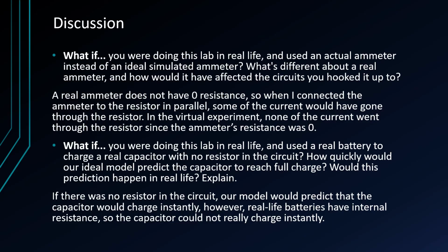What if you did this lab with a real ammeter? A real ammeter does not have zero resistance, so when I connected the ammeter to the resistor in parallel, some of the current would have gone through the resistor. But in the virtual experiment, none of the current went through the resistor since the ammeter's resistance was zero.